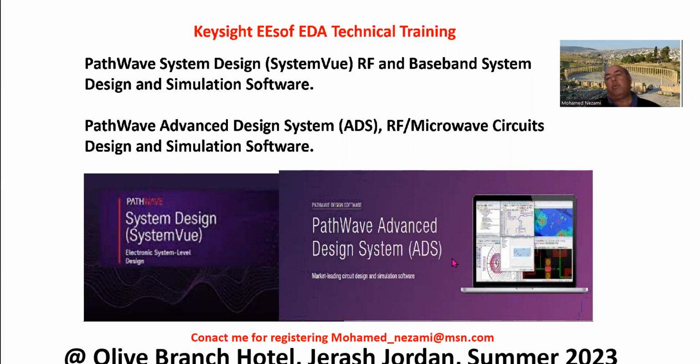The other training is where you go further down in the hierarchy of building the system, where you actually start building stuff and figuring out how you're going to tune it, get all the DC levels in there, the large signal model, small signal model, analyze, and basically come up with the real close to the final circuit schematics.